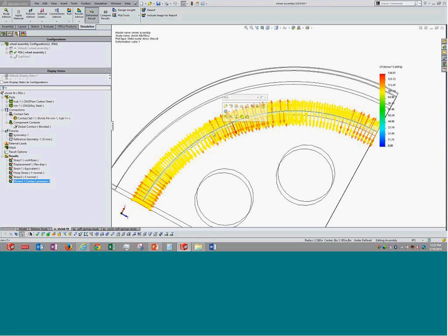Okay. So the other way around, the local contact, that is the shrink fit that we have created, is overruling the global bonded contact, and that is the one that is going to work here. If you remember, we discussed the hierarchy of contact. The shrink fit is the one that is going to overrule the global contact, so the global contact will not have any significance.